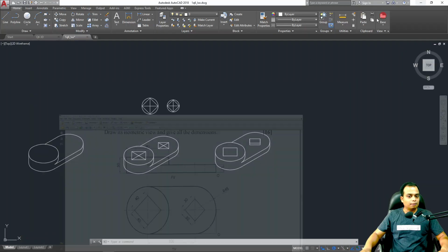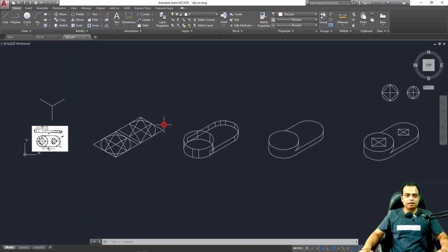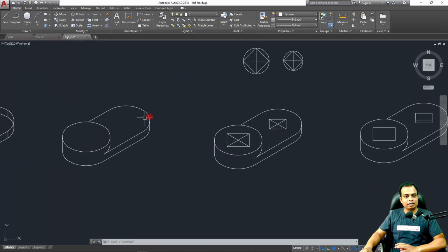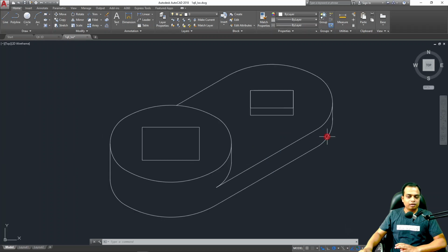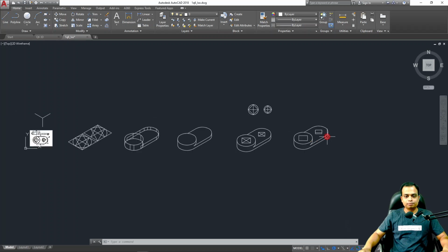And let me show you, my approach is going to be absolutely stepwise. Because if I start creating the entire drawing over here, there is going to be a lot of construction. You guys may get confused. So I am going to give you this timeline approach wherein I'll do some construction, I'll do some work, and then copy it again. Again I'll do modifications, copy it again, do modifications, and in this manner we'll finish the entire drawing. Make sure whenever you are making an isometric drawing, use a very light pencil. Hold it very lightly. 3H pencil to be precise. Shall we proceed? Here we go.